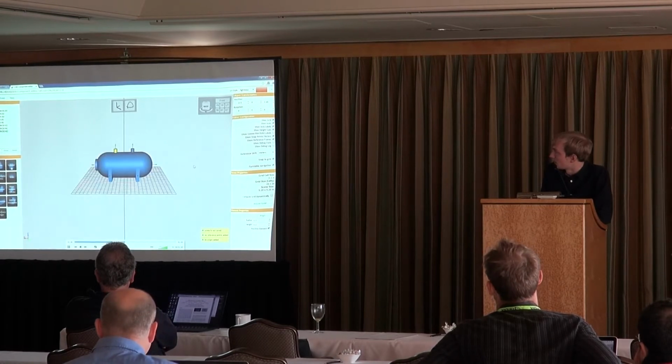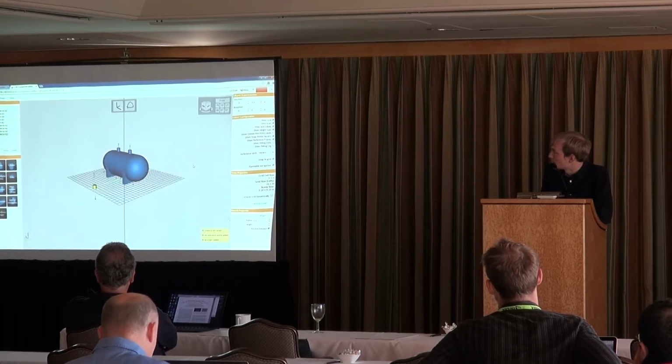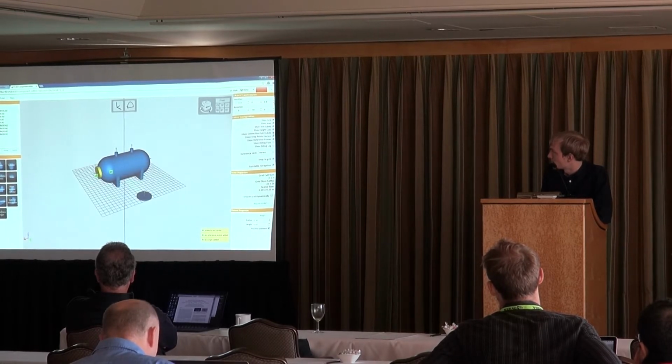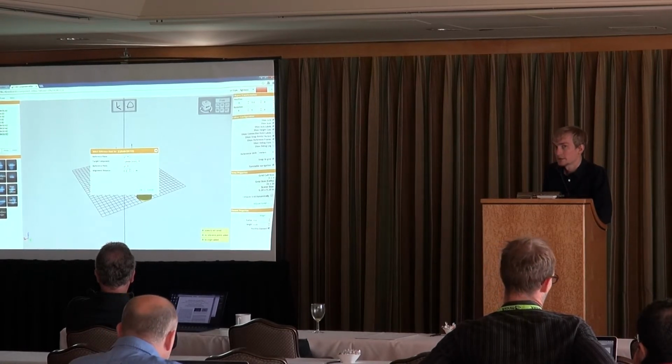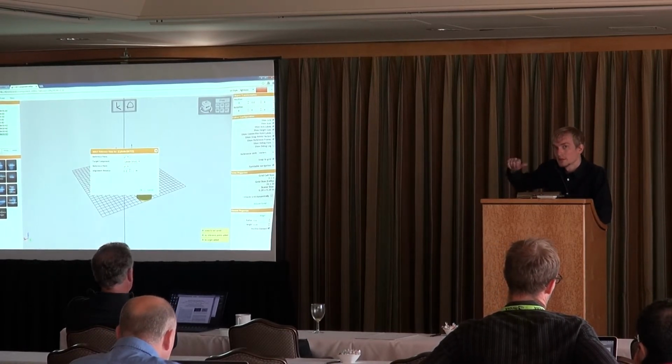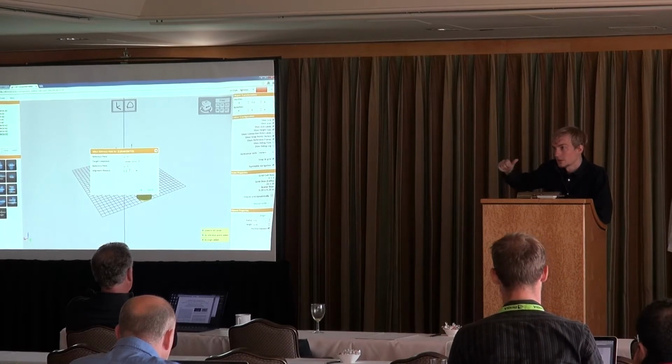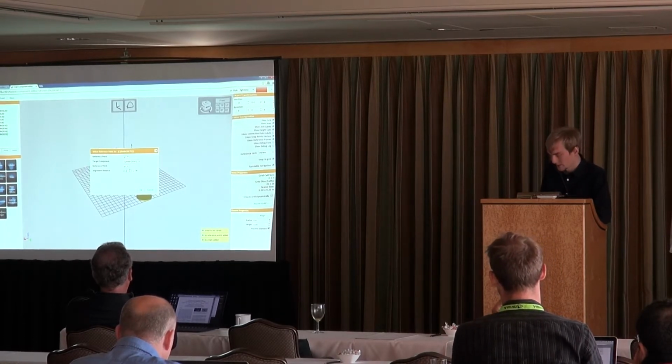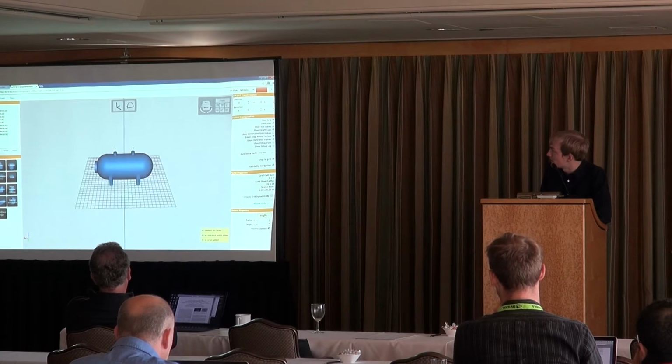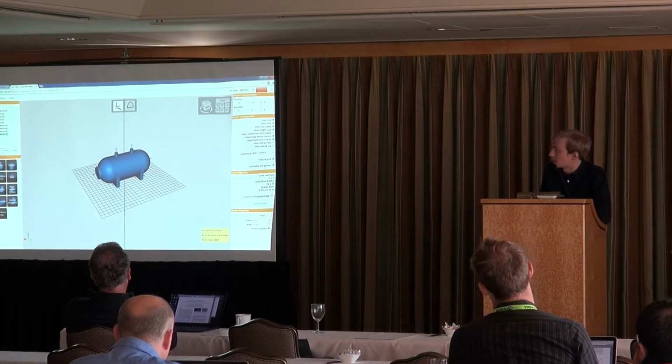If we want to place a component or a primitive somewhere, we can simply select another primitive, then select another reference point, and select an alignment distance. By using those vectors and points and this alignment distance, we can then simply snap the primitives together.